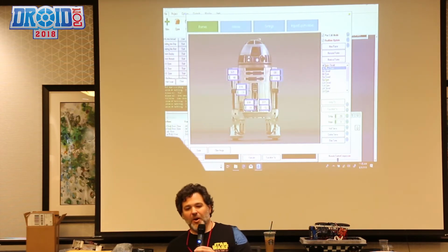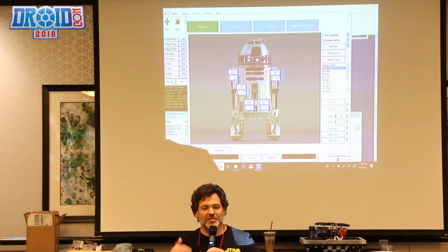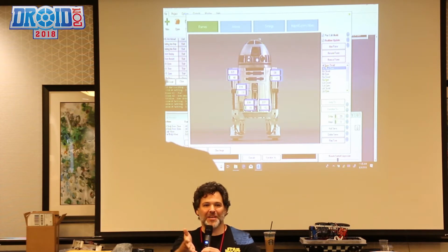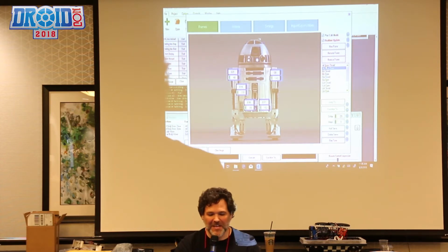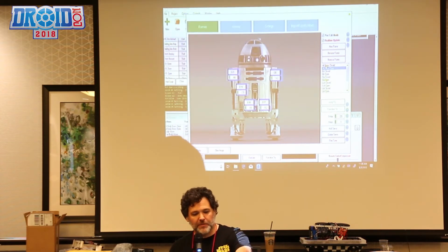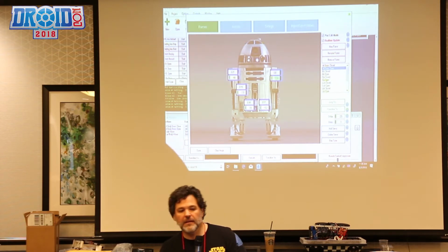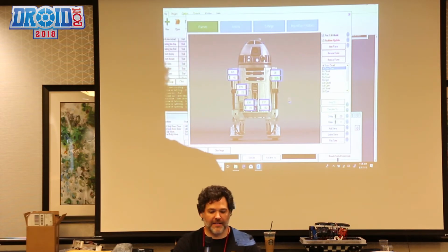Oh, yeah. Okay, sorry. I forgot to tell you that I adjusted the speed controller on the open and close in the adjustment. So normally I hear him slap closed and slap open, so I didn't think he was open. So when he's open, it's saying that on the left and right door, I'm using ports D21 and D0. And then to adjust this, I can simply grab this guy and slide it. So, is it moving? Yeah. How slick is that?